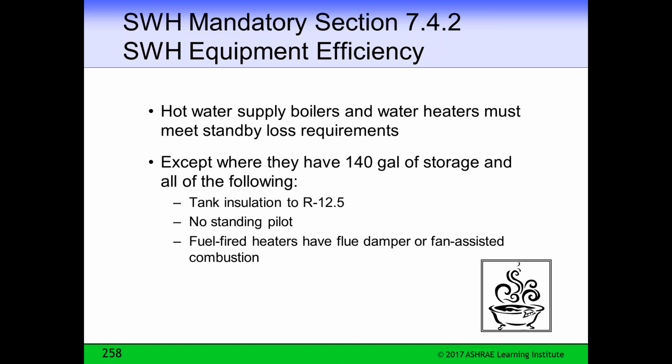HVAC, service water heating, mandatory equipment efficiencies. Hot water supply boilers and water heaters must meet all the standby loss requirements, except where they have a 140-gallon storage tank or larger. So this is a water heater with 140 gallons of storage. Those are not tested in general. You would have to have a one-off test, so we don't require that.